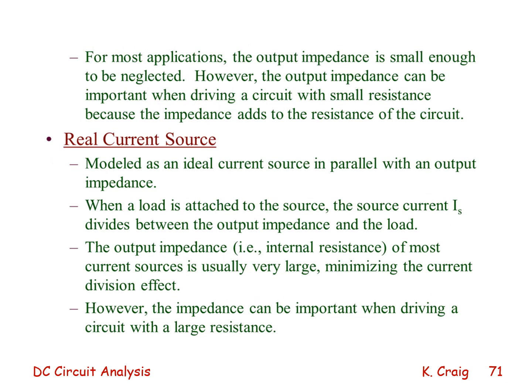For most applications, the output impedance is small enough to be neglected. However, the output impedance can be important when driving a circuit with small resistance because the impedance adds to the resistance of the circuit.